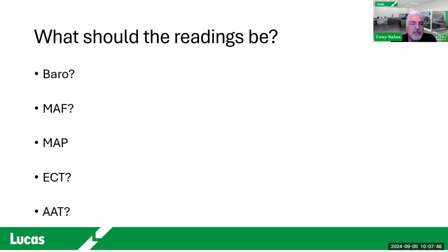And what you want to do is see if that actually matches, because we have seen some as off as half a pound. And that's enough to cause a drivability issue as well. Because remember, the MAP, especially the MAP, is what we call the load sensing sensor. So it's the one that indicates load along with mass airflow, but MAP is more critical. There you go. So in this case, we saw already what the hertz of frequency we should see, for example, on a Duramax for mass airflow, right? Actually, it was a Ford.